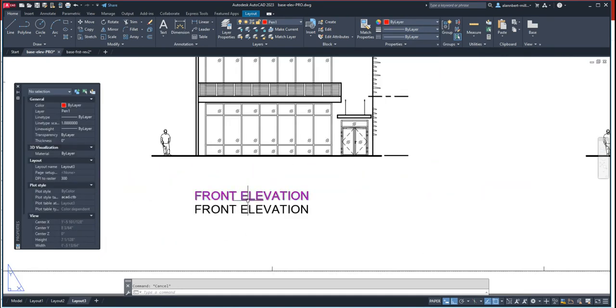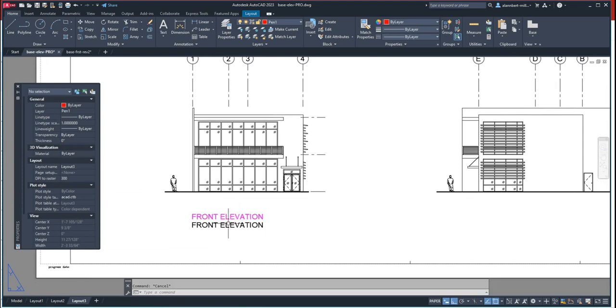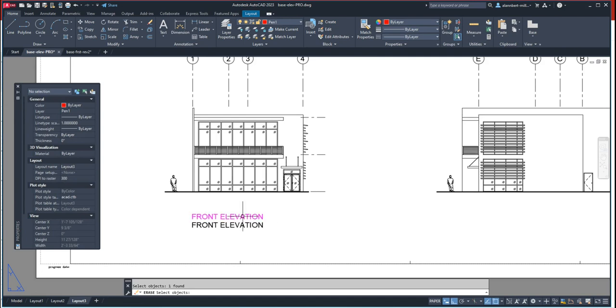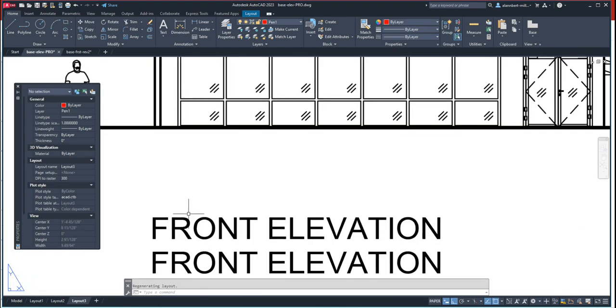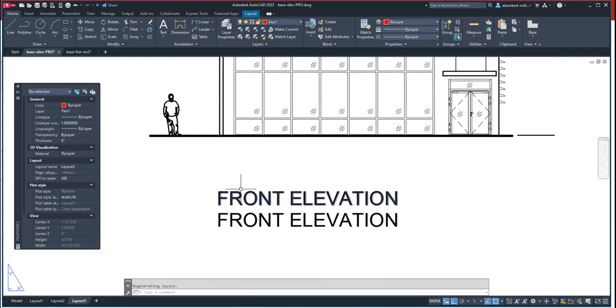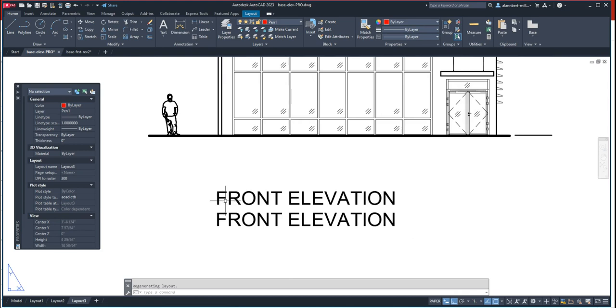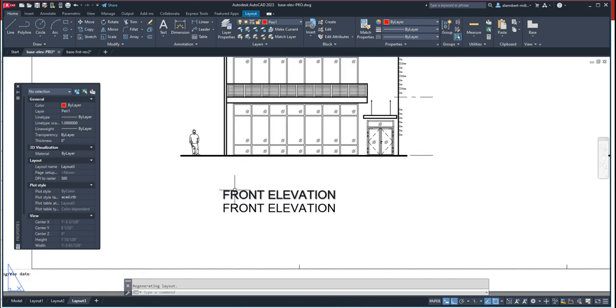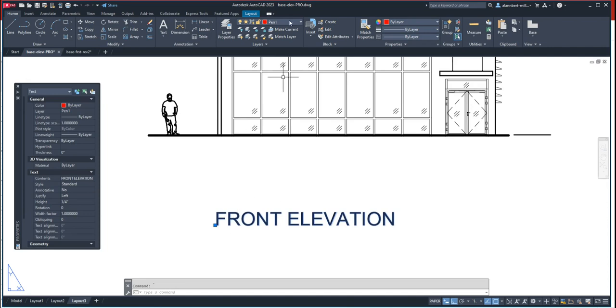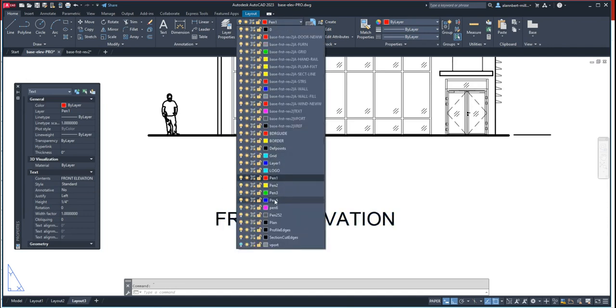Now, to me, this is a little bit small, so I can change the height of this one. I'll erase one. Do a regen. Sometimes, so that AutoCAD will be much faster, it doesn't really change the color or affect the black and white mode or plot style mode until you regen all or regen. So let's just erase this and leave this at color 5 or something.